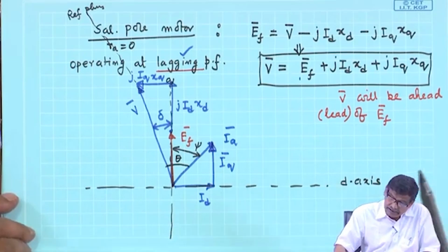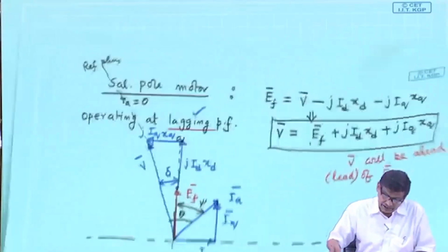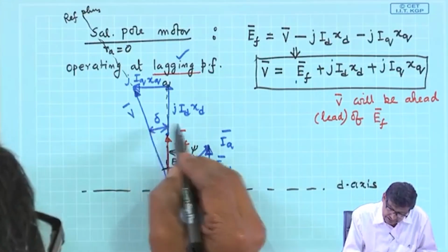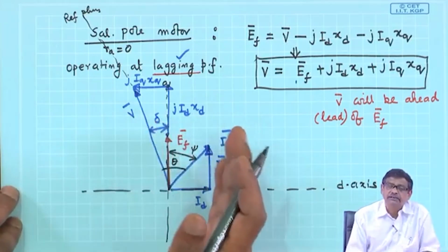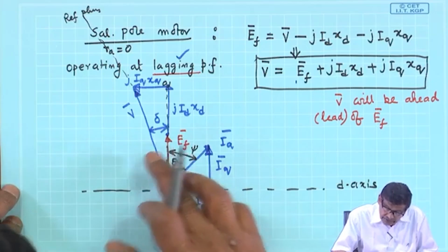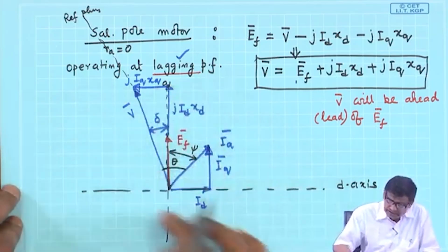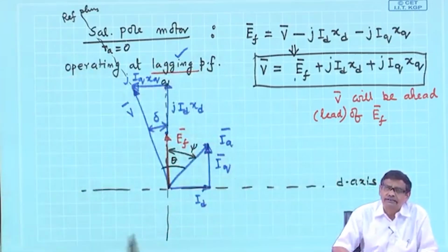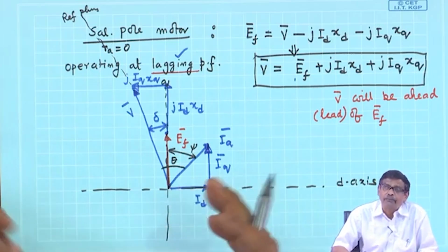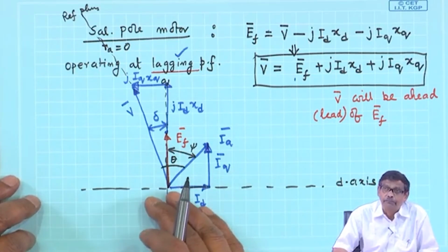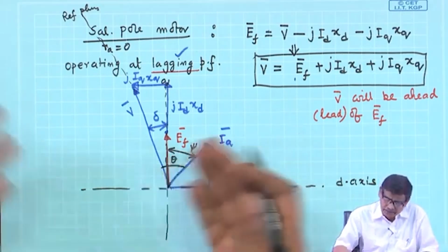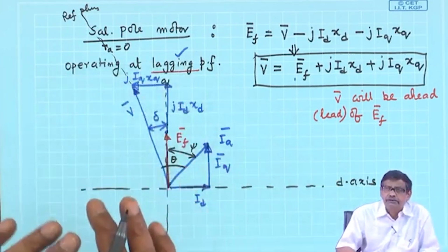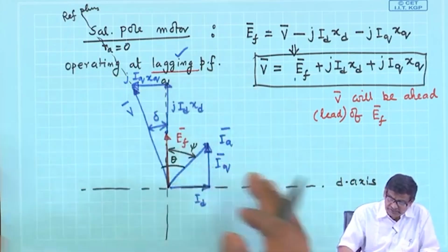Let me once again draw, and you see in case of motor mode EF is, and this angle is delta, EF is behind V, because the direction of torque reverses, and all things are there. So, if some parameters are given, you can apply the properties of triangle, this that, to solve simple problems, apparently complex, but very quickly. Okay, armature current, power factor angle, these are given, draw the phasor diagram correctly, then you are through. See which sides are given, things like that.